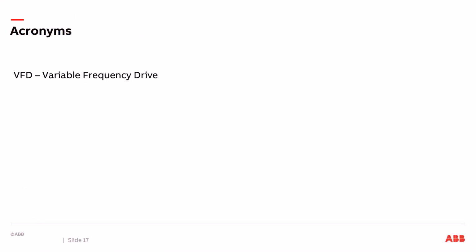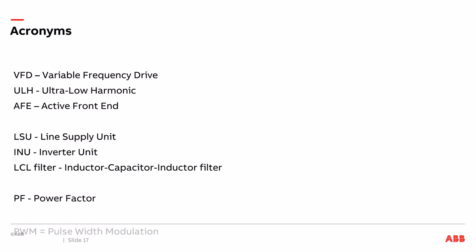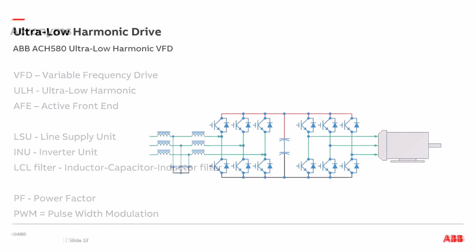VFD is a variable frequency drive. ULH is ultra-low harmonic. AFE is active front end. LSU is a line supply unit. INU is inverter unit. LCL filter is an inductor, capacitor, inductor filter. PF is power factor, and PWM is pulse width modulation.